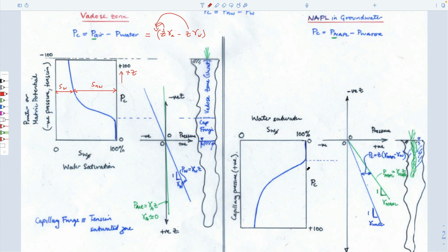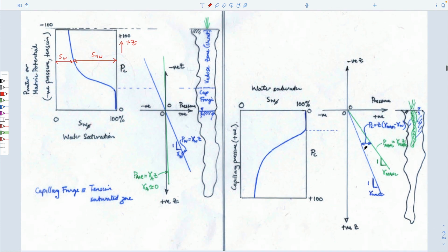And if we turn it upside down and flip it, then the same holds for the capillary pressure versus saturation curves, where this would be again, the saturation of the non-wetting fluid and the saturation of the water. And it changes from being 100% water saturated at this one with none of the other component there, to being a mixture. And of course they sum to unity because of those. So that's kind of the picture.